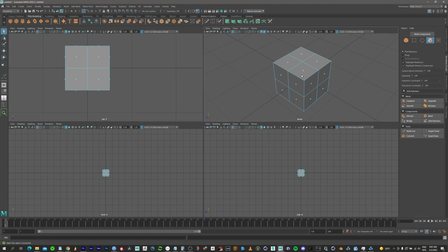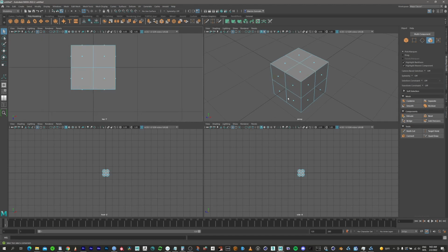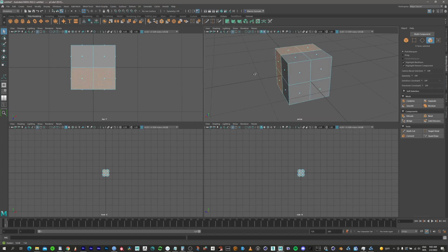So what is the advantage of this? The main advantage is that now, here in the top view, I can select only those faces. So if I click and drag to have the selection box, I just need to avoid the other points, like these points here, because then I would be selecting those faces. I can select only those two here, and I'm going to select only the faces that I wanted. If I do want those, I just have to select those points too. Very handy, gives you way more power during modeling, in my opinion.